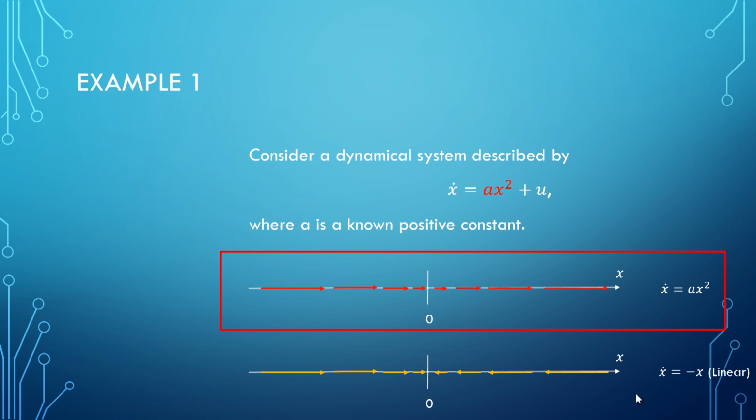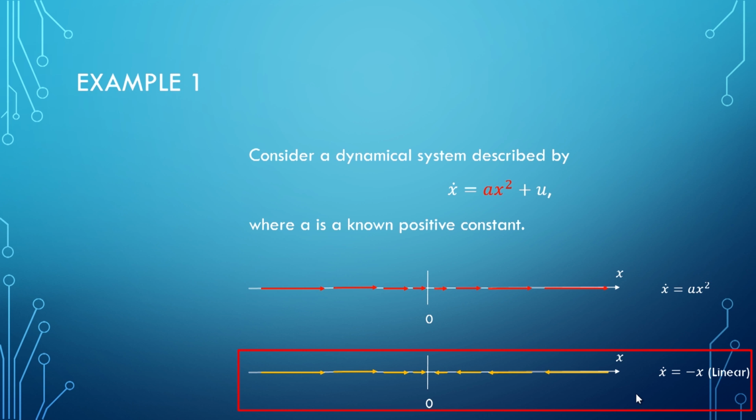And this is the open loop dynamics where you don't apply any control input, right? So it is zero. And this is the dynamics, which is unstable. And after you apply a control input U, you design a controller and substitute into the system, you get this closed loop dynamics, which is stable. And this is the objective of designing the controller that stabilizes the system, which might originally not be stable.